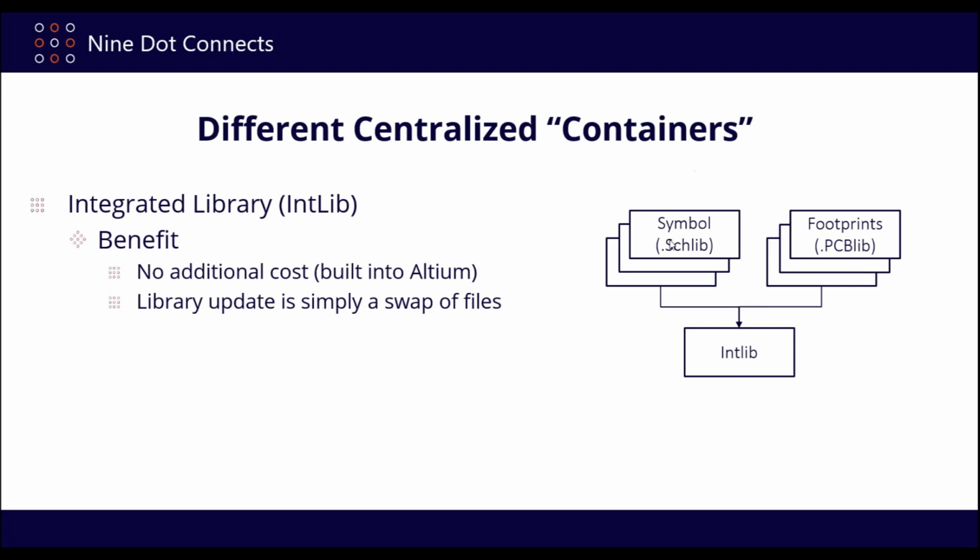And then in Altium Designer, they'll take those files that they worked on, the symbol and the footprint, and they'll compile it into what's called a .intlib. That .intlib is put into a public area, and as long as they maintain the exact same name, all they need to do is just update the file that's already in this public area, and everything will work really smoothly, because Altium just points to that file and it points to the name of that file and the location of it.